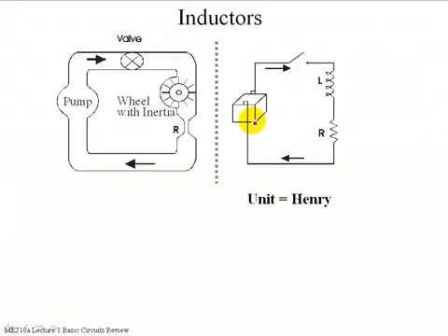We're going to deal with inductors, but not really as explicit components that we will put into the circuit. But all the motors and solenoids that we're going to deal with have coils of wire in them that make them behave like inductors. So it's important that we're aware of that behavior. And the behavior is that the inductor resists changes in current through it, and it responds by creating a voltage drop in order to resist those changes in current.